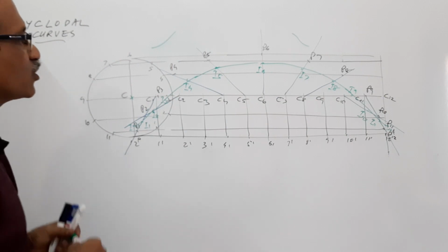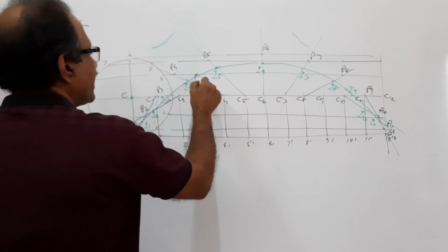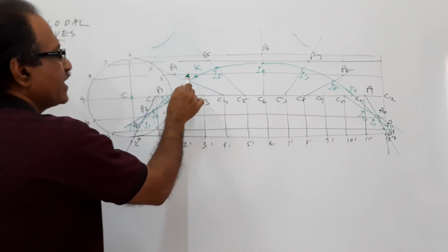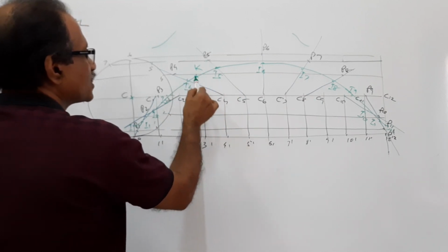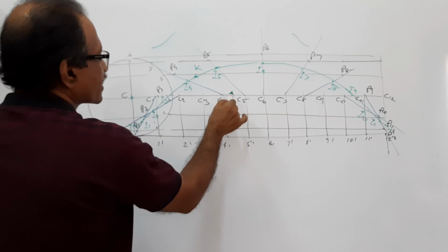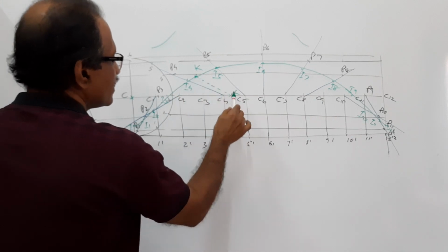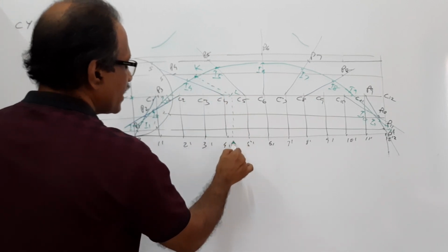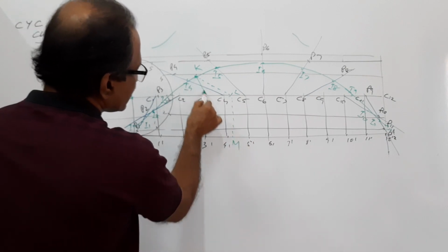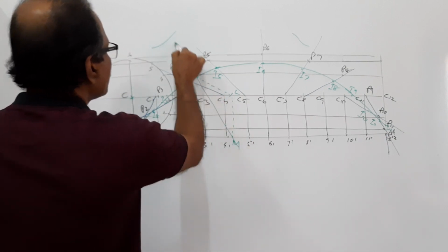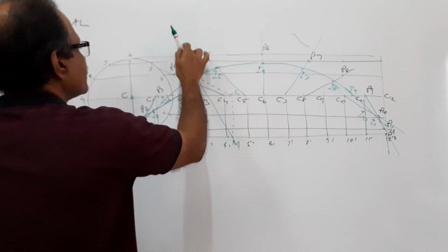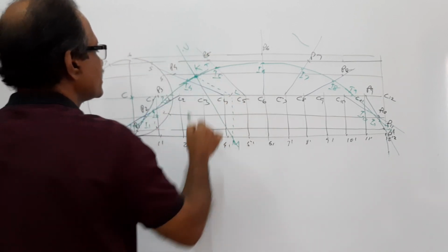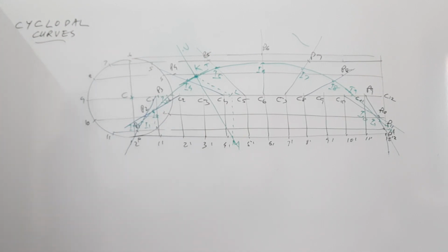Now, suppose you want to draw the normal and tangent at this point called K. K is between I4 and I5, with 18 mm radius. So between C4 and C5 there must be L. Take 18 mm and cut an arc. You get L. Drop L down. M. MK is the normal. Perpendicular to that is the tangent. This is the normal. This is the tangent. This is the case of an inferior trochoid.